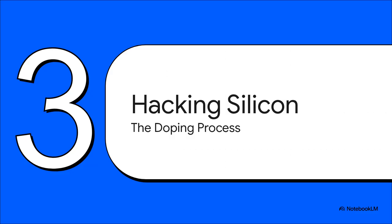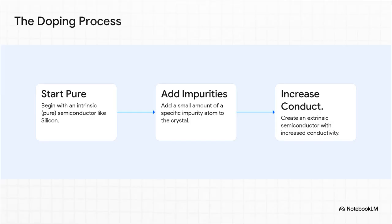You know, a pure semiconductor by itself is like that toll road with all the booths closed. It's kind of neat, but not very useful. But this is where we get really clever. We can fundamentally change it. We can hack silicon through an incredible process called doping. Doping sounds really complex, but the idea is actually genius in its simplicity. You start with an unbelievably pure crystal of silicon, and then you intentionally sprinkle in just a tiny amount of atoms of a different element. And that tiny addition of what we call impurities completely rewrites its electrical personality.